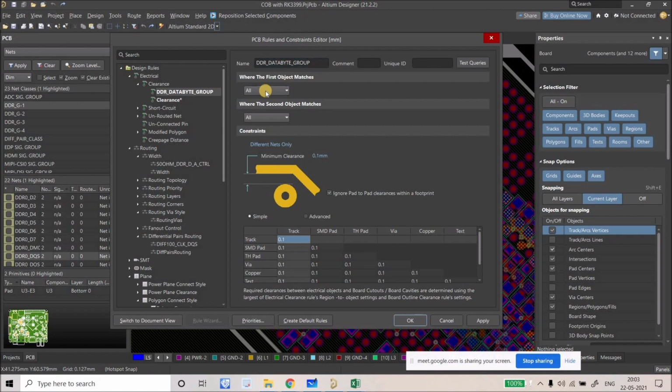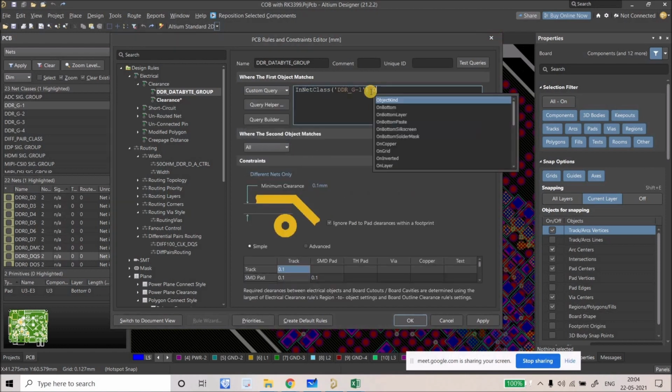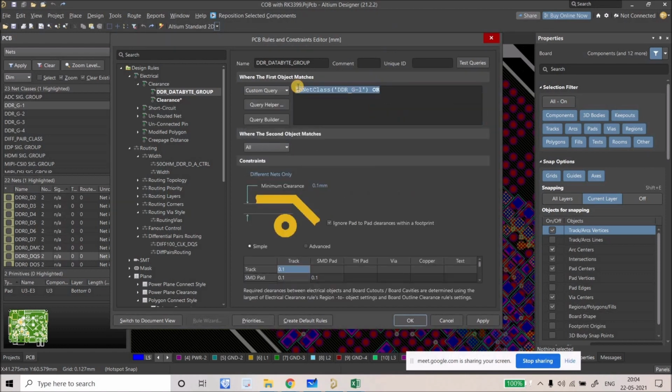All right. Now you have to select a net class. What are those net classes? Anybody want to tell me? One will be this one, then we'll create a custom query and use OR, just copy it. All 3 types of signals will be covered in data group 1: the differential DQS signal, the single-ended data mask, and the single-ended data bits.